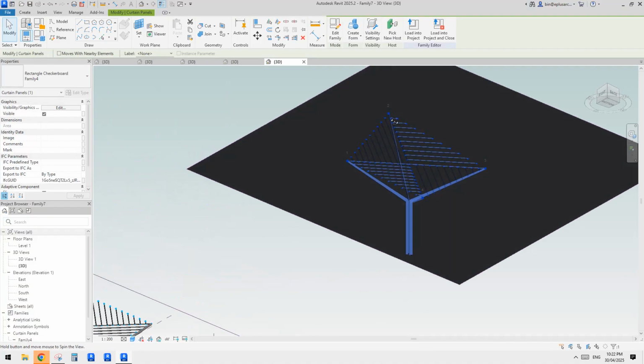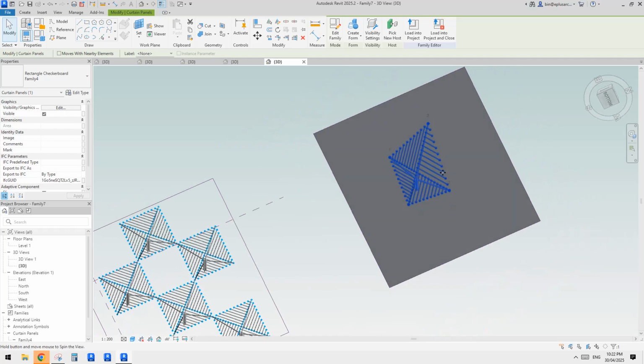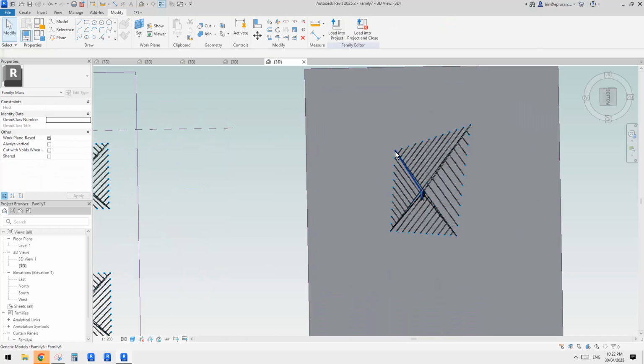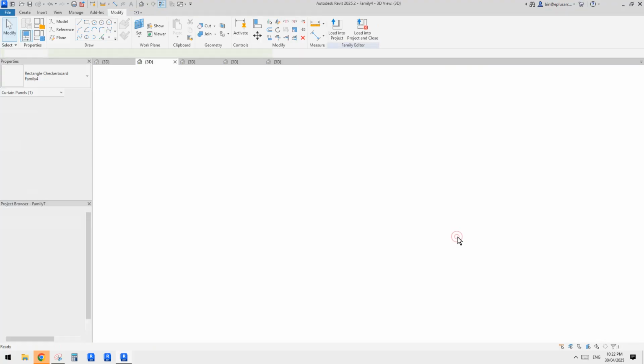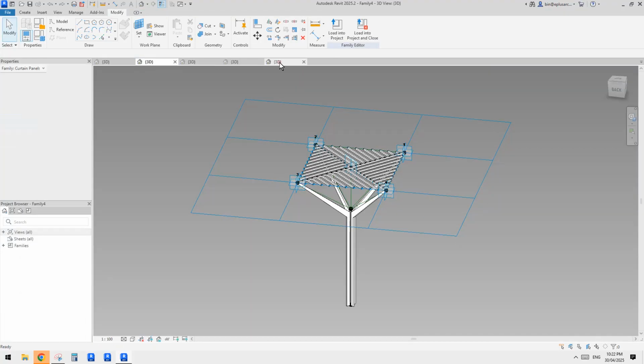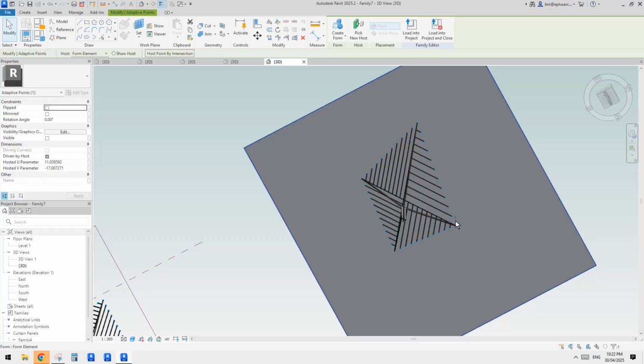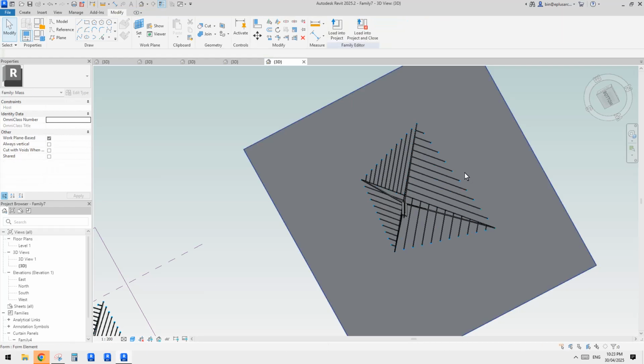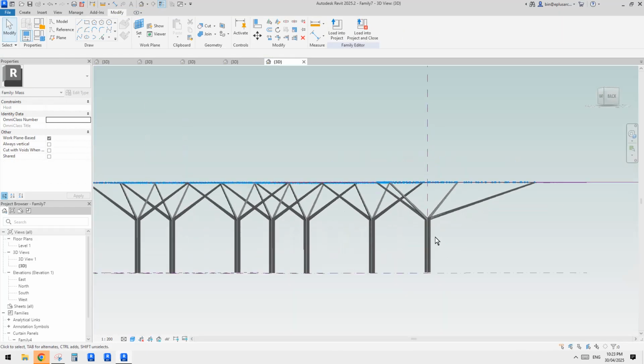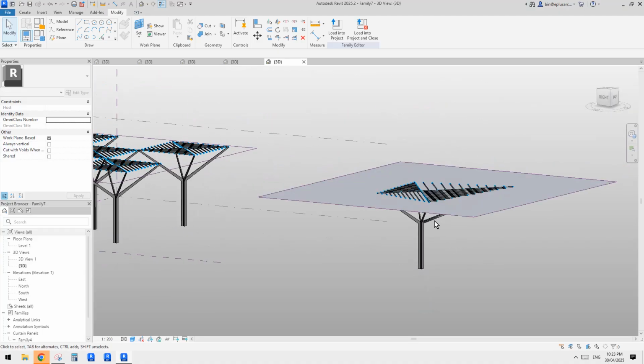So you can see you can also manually place. It doesn't need to be rectangular or square. You can place all these 4 points wherever you like. Oh, hang on, accidentally double clicked again. You can also move your cursor onto that point, trying to pick that adaptive point. See the number 3, and you can pick new hosts and then move it. Or you can drag it. I believe you can just drag that point to wherever you like. Okay, so this is it. Don't worry, this is just an example.